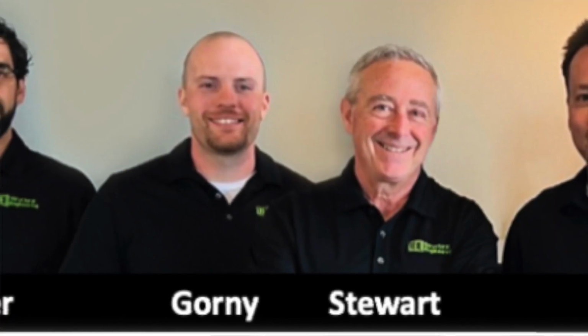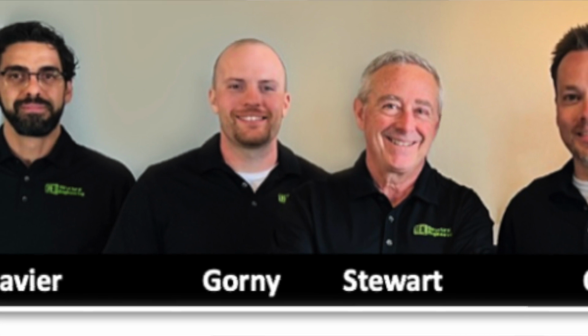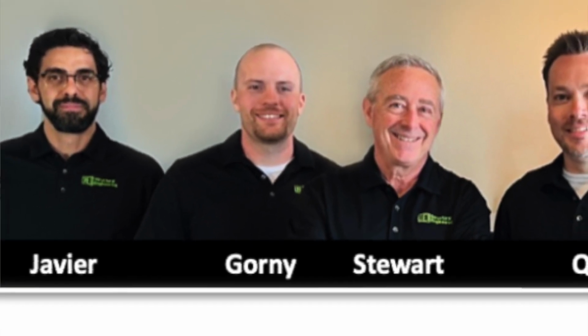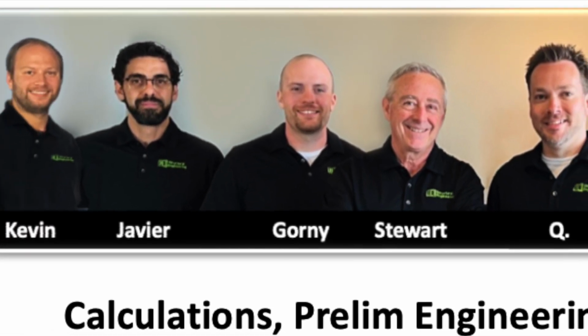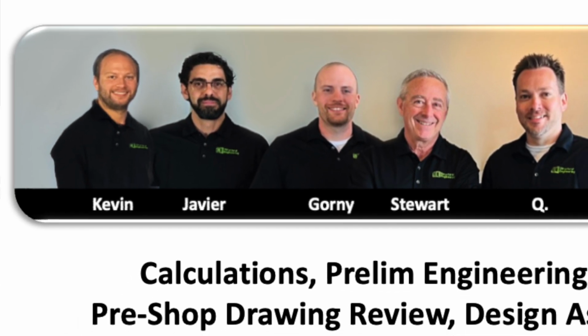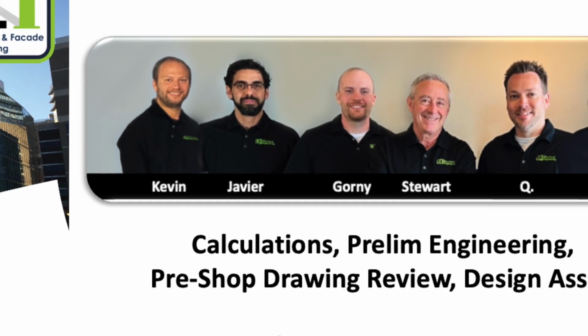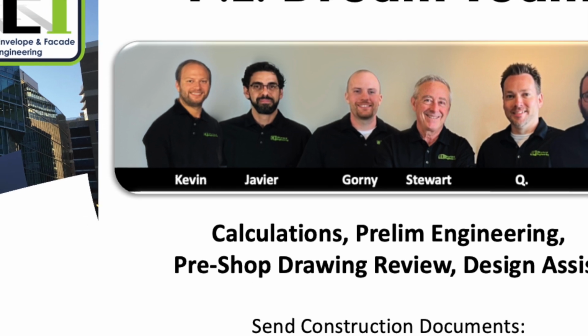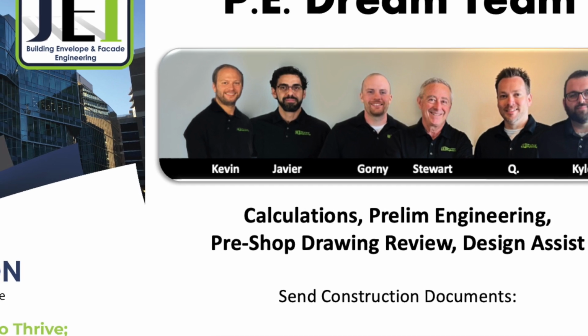I had an ASCE PDH that talked about some of this stuff. We've had a few around the office now where it's a canopy, but it's ASCE 7-10, and some of this canopy stuff isn't even in that. So what I got from her, who did the PDH, is I just run a few different scenarios. I'll run it as an open structure, and I'll run it connected to the building. Because she was like, sometimes you just have to do that.